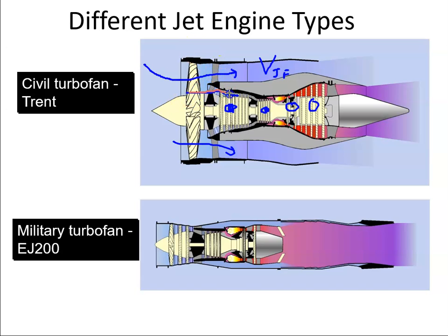Okay, so the hot stream air comes through here, gets burnt in the combustion can, out through the turbines and out the back. The turbines here, they drive the fan and the low pressure compressor, and the high pressure turbines drive the high pressure compressor. So there will be some jet here, so I've called this jet of the hot section. And then our thrust will be the combination of thrust from the hot section and the cold section. But most of the thrust comes from the cold section.